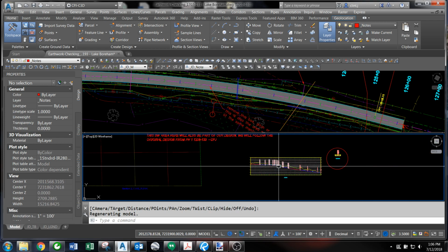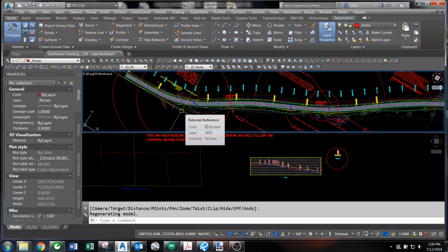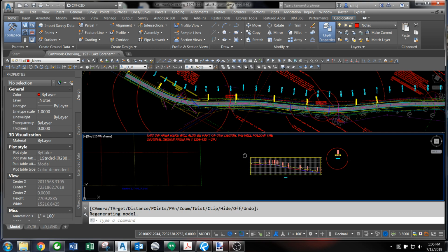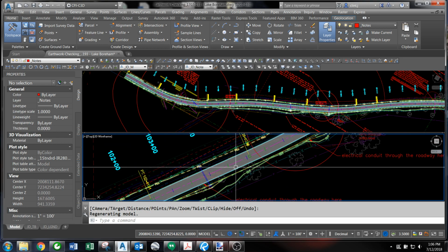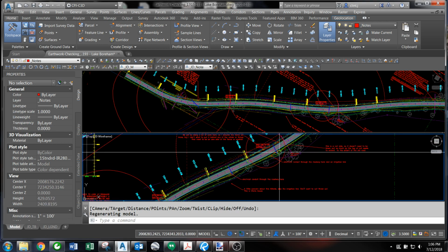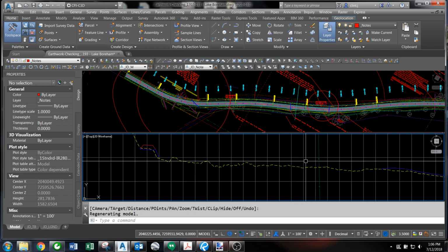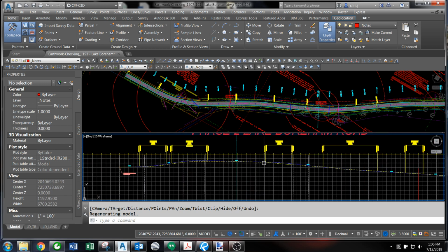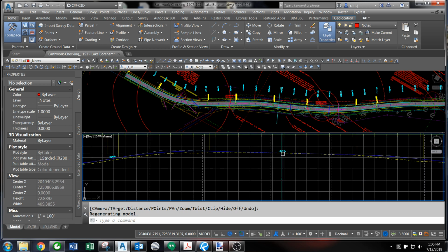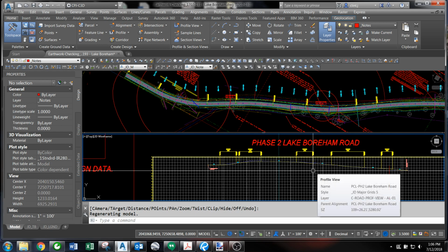Anyway, I wanted to show you that this is why we have different alignments, profiles, targets, things on the corridor that we're trying to do, so that we can control these ditches more than just letting the center line control, because the center line just didn't have a lot of slope. We just didn't have a lot of slope sometimes to mess with on these roads.